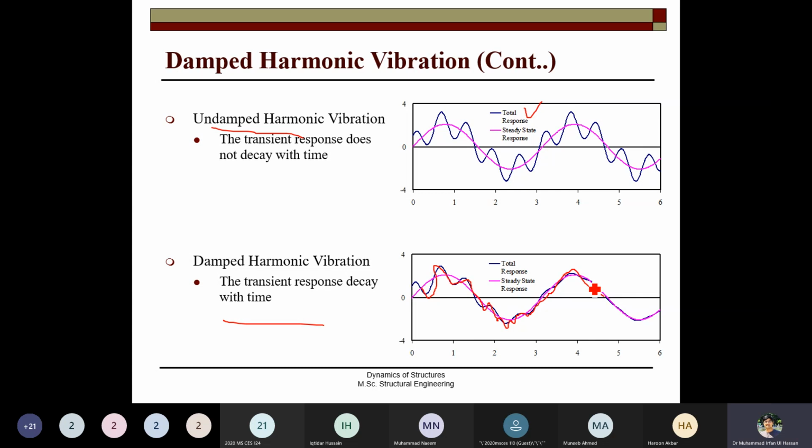So you see that when some machine is started, initially the structure has very high vibration, and after a few minutes the vibration becomes constant. So the reason is that the disturbed response initially is due to the transient response and due to the internal structural effect, damping effect. They are present, and due to the damping later on these are reduced.